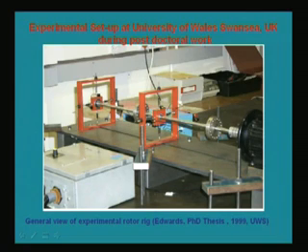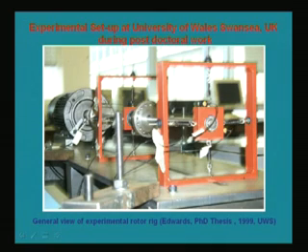These are all laboratory setups so that we can simulate real life turbines, because any method for finding faults in the machinery can be checked in these small setups, and then it can be applied to the real machineries. So here also you can see various sensors closely. Here there is an accelerometer on the bearing block. They are measuring the vibration of the bearing.